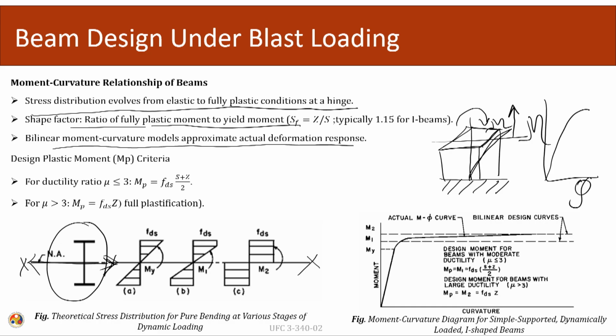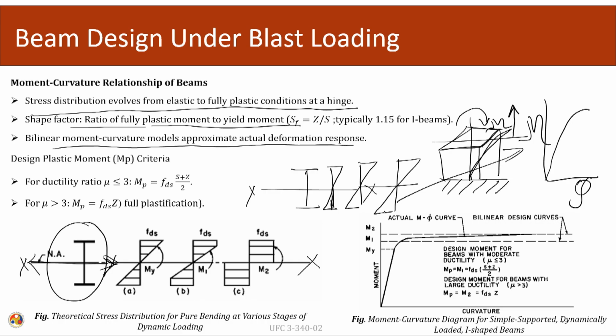The definition of the neutral axis goes like this: the axis in which the net strain is 0. So, at the starting, what will happen is that at the two peripheries, if this is my cross section and this is my neutral axis, at the two peripheral zones strain will be developing. As the moments are applied and the beam is bending along the x axis, strain will be developed at the two ends. So, as we increase the applied moment, the value of strain will keep on increasing.